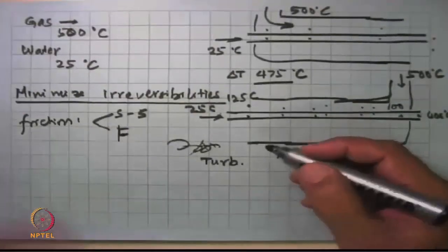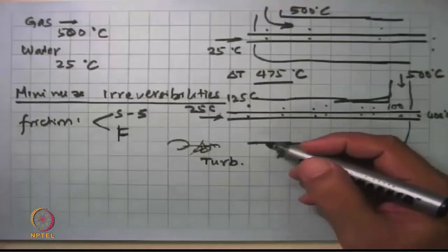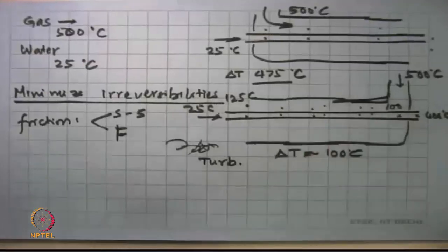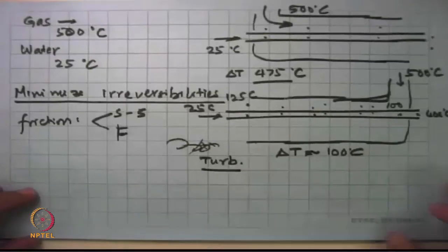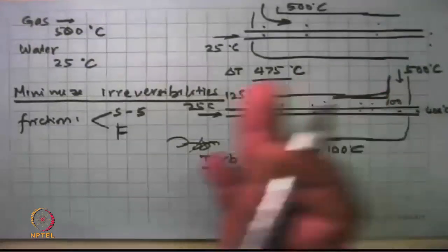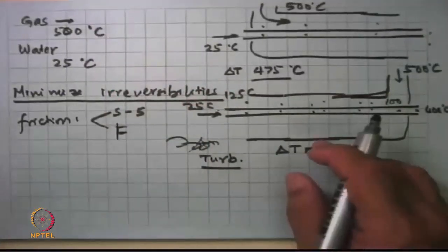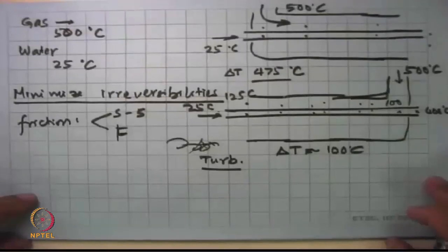And that is doing nothing but dissipating energy, the kinetic energy of the fluid particles. They are rubbing on each other, dissipating because of friction, and it generates heat. So we try to minimize that, and so we make the surfaces as nicely aerodynamic as possible. And that's what you see whether you're looking at a ship these days or an aircraft engine or a pump.